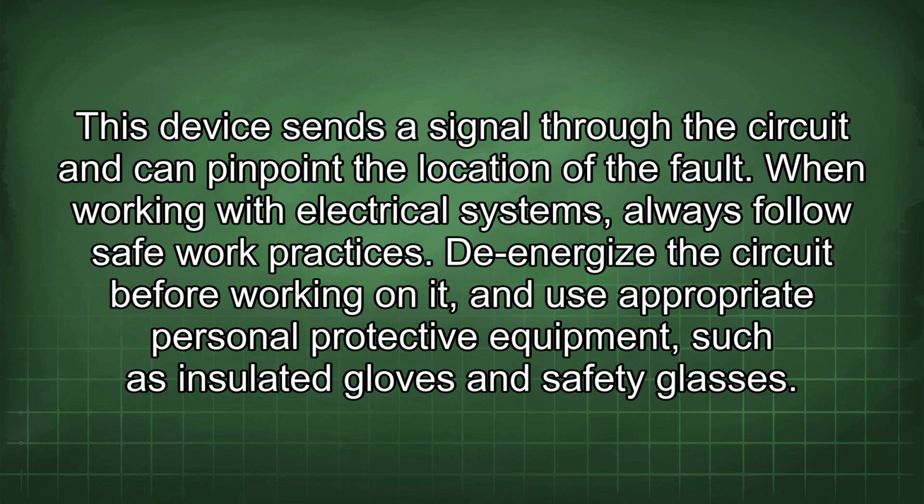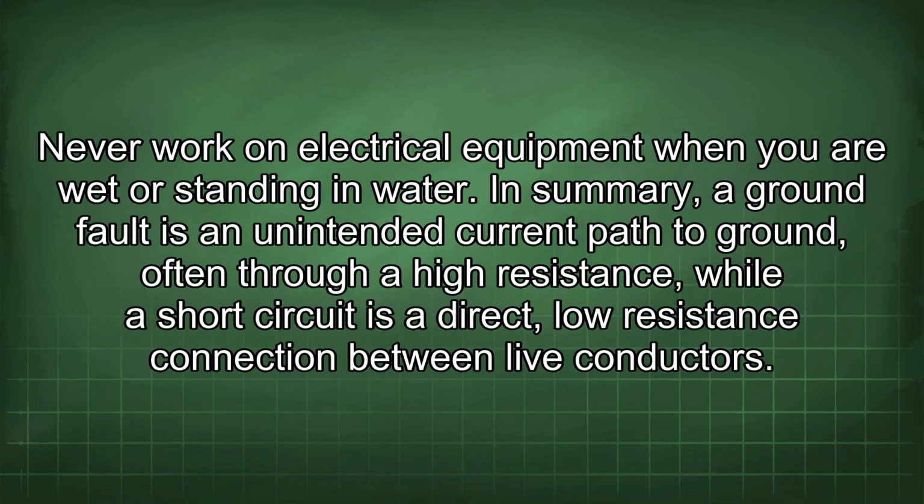When working with electrical systems, always follow safe work practices. De-energize the circuit before working on it, and use appropriate personal protective equipment such as insulated gloves and safety glasses. Never work on electrical equipment when you are wet or standing in water.